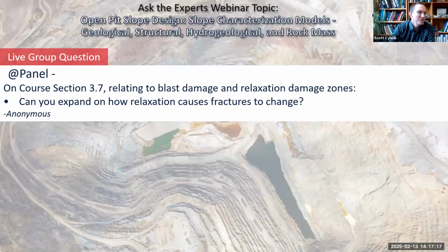So in the situation we're just describing, we're well above the water table, and maybe under normal conditions these fractures are dry. But if there's a fine grained coating on the fractures, and we get water in there, we can also have the strength drop just from adding the water alone, which is another bad factor potentially contributing to slope failures.